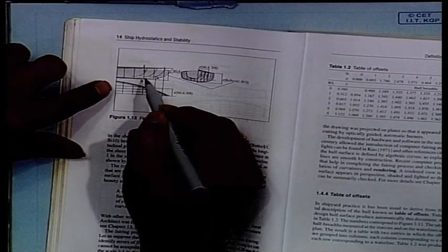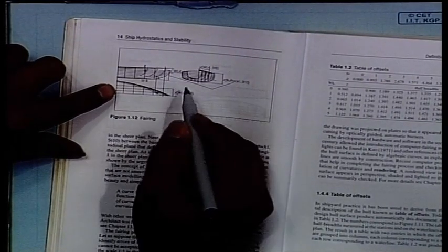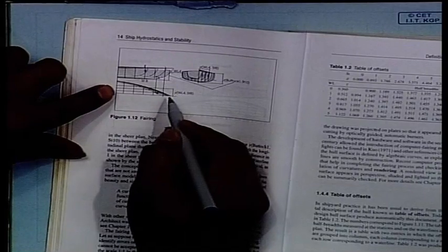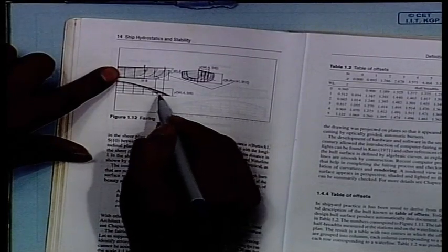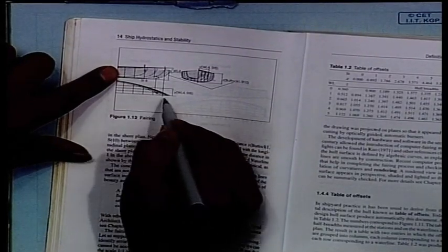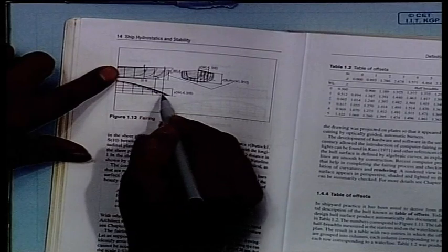Now, in the top view it obviously should represent waterline 4 and station 8, that is what it represents in the front view. What it means is that in this you have a waterline like this. So, the intersection of that waterline and that station here and here will be in one straight line, right.